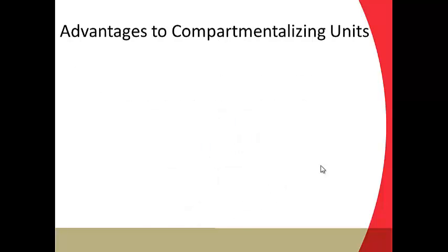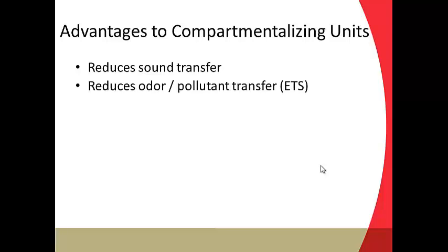There are certainly a lot of advantages to compartmentalizing units. It'll reduce sound transfer, and that becomes very important in a dwelling like this. Reduces odor and pollutant transfer. Reduces wind effect. If you get the wind blowing on the outside wall, air will have to leak from that unit to the hallway, and then the hallway to the adjacent unit, and the adjacent unit to the outside.